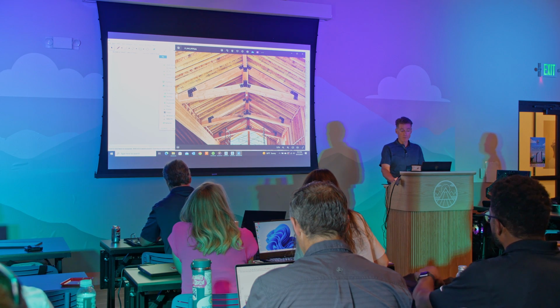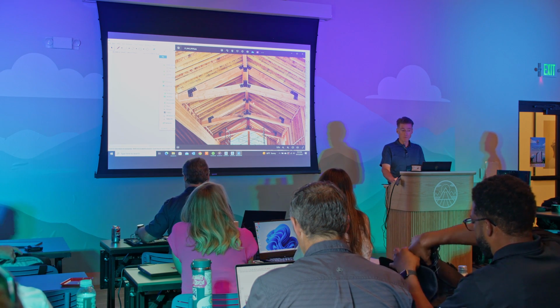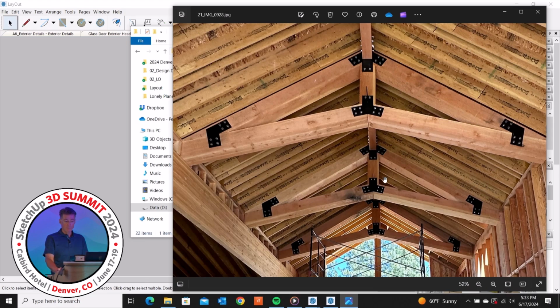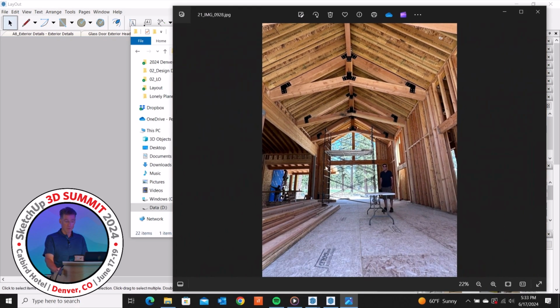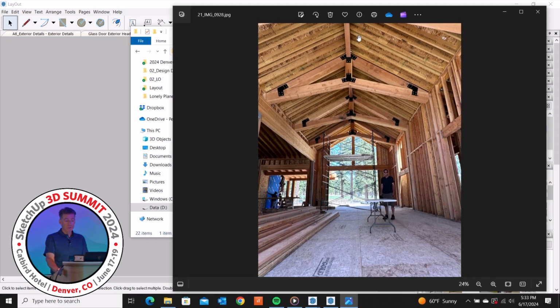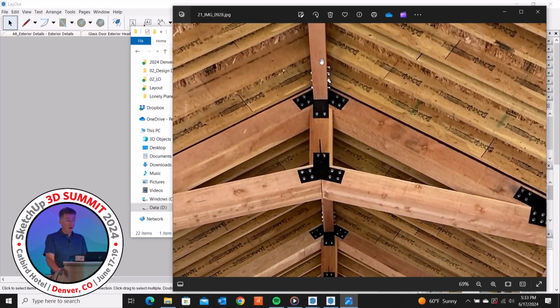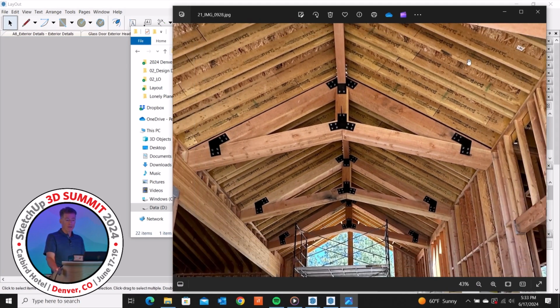Suspended from each one of these is a big round light fixture. It's a beautiful spot, and it's huge. I mean, the volume in this room is really amazing. The joists are just spanning to the ridge beam. Oh, they get covered. So they get first a layer of 5/8 drywall, and then they get 1x8 decking that is matched to the outside. So it looks like the decking just continues to the outside. And then the rest of the finish is just drywall on the inside.